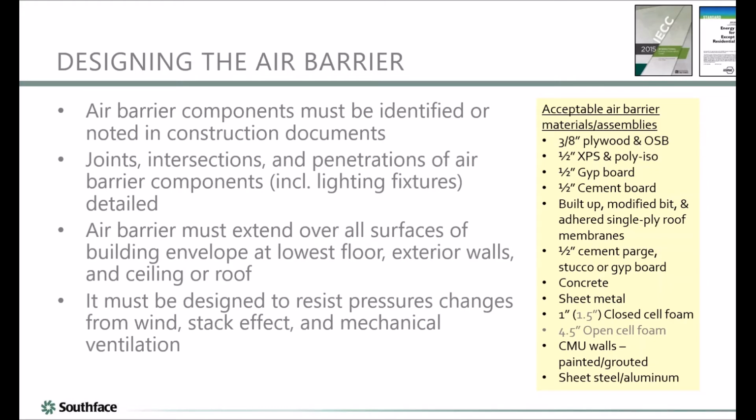Sometimes it's more than one type of material that makes it up, but you need to identify the primary air barrier. For example, in exterior walls on new construction, that's usually the sheathing. Make the sheathing tight, and your walls are going to be tight.